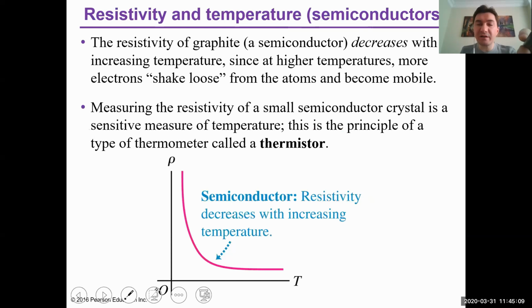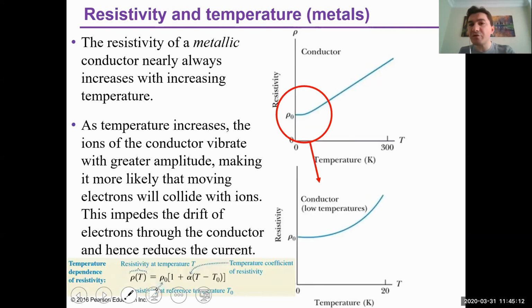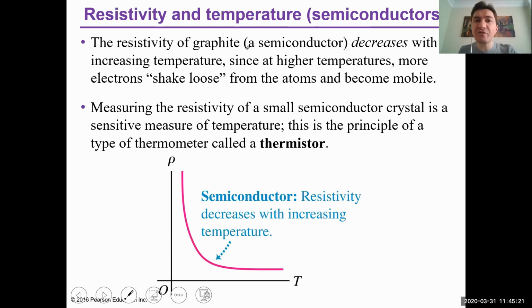So what about semiconductors? But let me also remind you that the application of that property of the metals is very important. So the resistivity of graphite, for example, here decreases with increasing temperature. This is the resistivity of semiconducting material. This is the increasing temperature. But you see here that at low temperatures, resistivity is huge. It goes to infinite, okay? But whenever we heat the semiconducting material, resistivity goes down and then conductivity increases. Semiconductors become more conductive at high temperatures, okay?